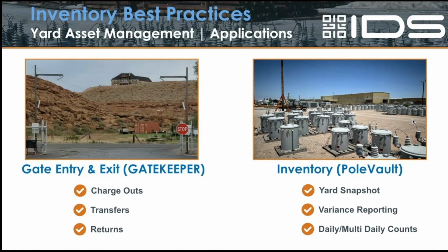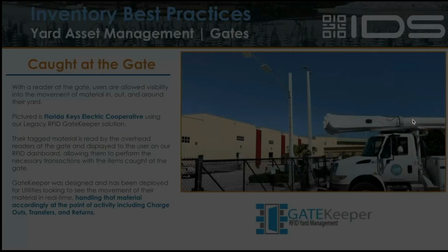Currently, in all of our installations on V2 right now, we're running either at 15-minute intervals or 30-minute intervals, which I think most of you would agree is plenty frequent enough. I don't think anybody needs that information any quicker than that. If we go any quicker than 15 minutes, then we're going to start using up the energy that's harvested from the solar panel, and we would want to hardwire it. Go ahead.